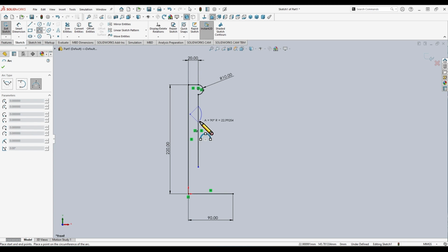And then I can move my cursor to the right, and you can see it already snapped into place because it's trying to put that center point on my line itself, which is where we want it. But I'm going to give you an example if I go too far. So if I keep going to the right, eventually I can make this sketch relation where it kind of looks like Pac-Man, where again, it's trying to make a 90-degree sketch relation in the arc there, denoted by those dotted lines. It would be a 90-degree angle between the two of them. But what we're supposed to do in this picture is we're actually supposed to get that center point of this arc to line up with the line that we drew.